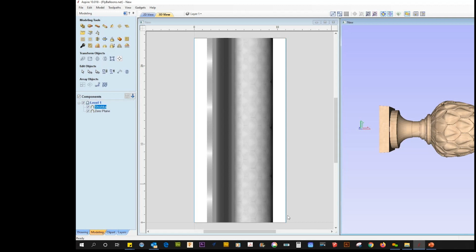I also suggest using a ramp plunge. This also takes stress off the bit. Normally, I would run maybe like a 3/8, or you can run higher. It would do a zigzag as it engages in before it starts initializing the actual cut. And then we would save this as just a regular rough.